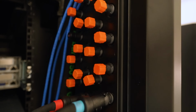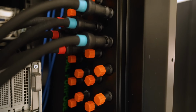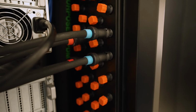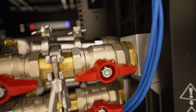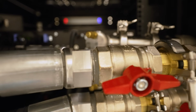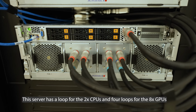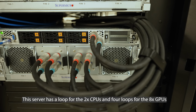And a really good example of that is that in these systems, in the racks that have direct-to-chip liquid cooling, you typically will have things like these just giant liquid or water distribution blocks, kind of like you would have a PDU on the side of your chassis or in a rack mounted configuration, but you have to have some kind of distribution to be able to manage all the loops. The systems that we're actually taking a look at, they're not just like a single loop per system. Oftentimes the AI accelerator systems will have to have multiple loops per system, and then there are multiple systems, so you just need a whole bunch of loops going on, and that's why you have these kind of distribution blocks.